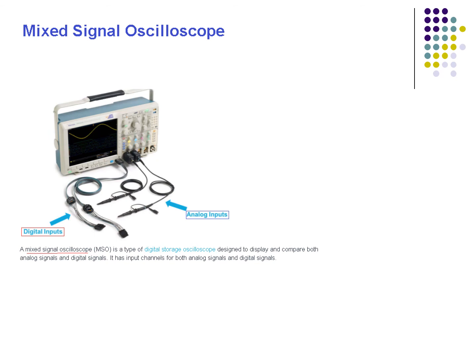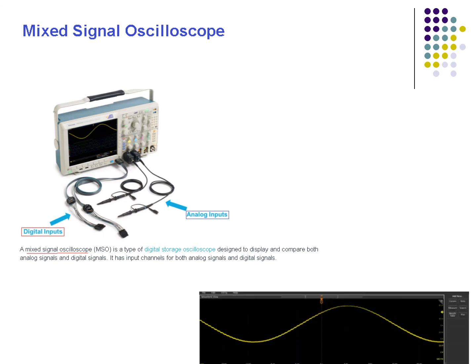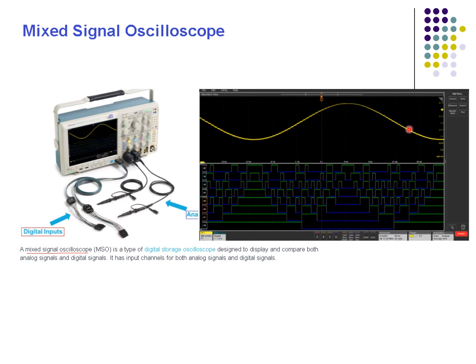Okay, here is an oscilloscope. This is called a mixed signal oscilloscope. Now this has both the analog signal capturing capability, so the analog input comes with these 2 probes, and it also has the digital input signal. Now digital, as you know, in digital electronics or in modern day communication, everything is digitized. So it has either a 0 volt or 5 volt level. So this oscilloscope can show both digital and analog, as it has been shown here. This is the analog signal and this is the digital signal. Previously for viewing digital signals we used to use digital signal analyzers. Now this oscilloscope has made that redundant, and now both types of signal can be presented on the oscilloscope.